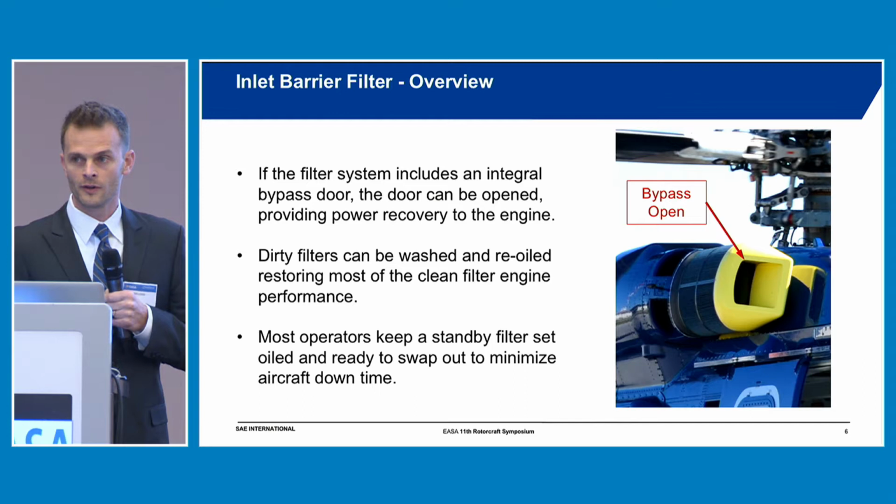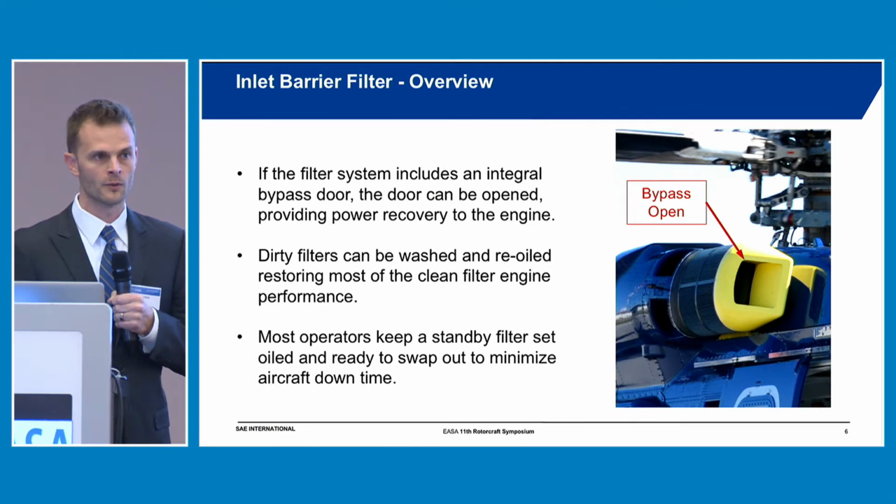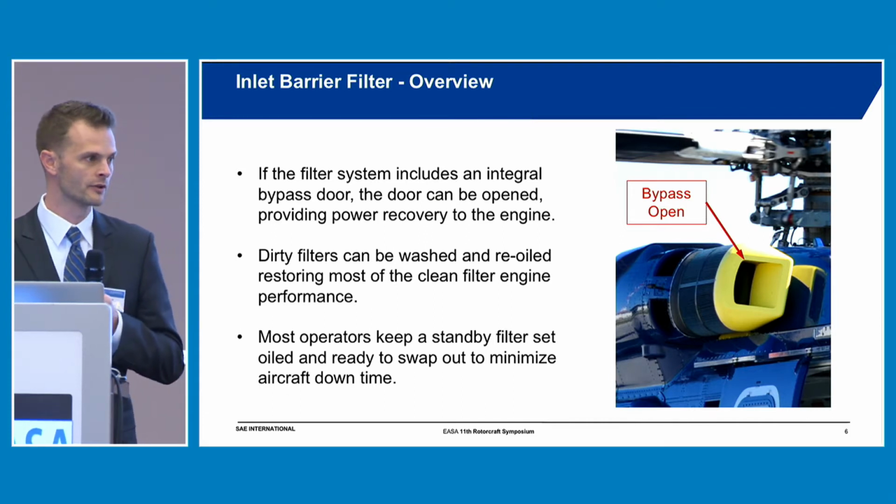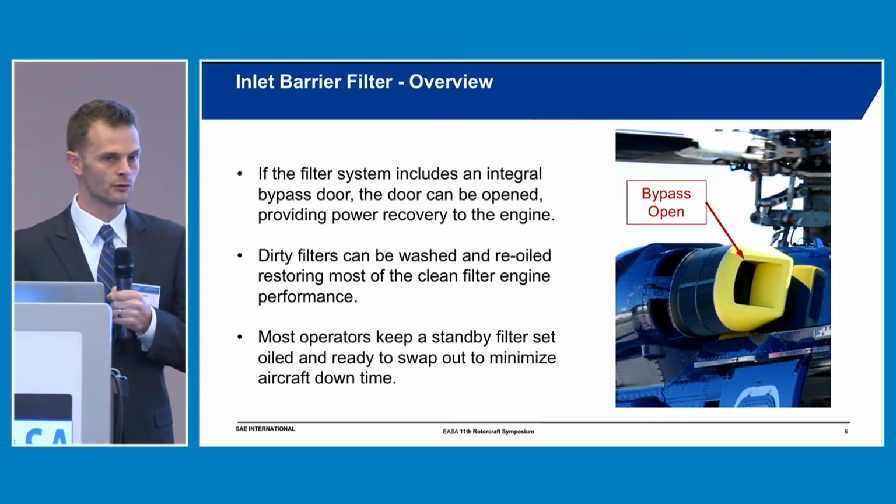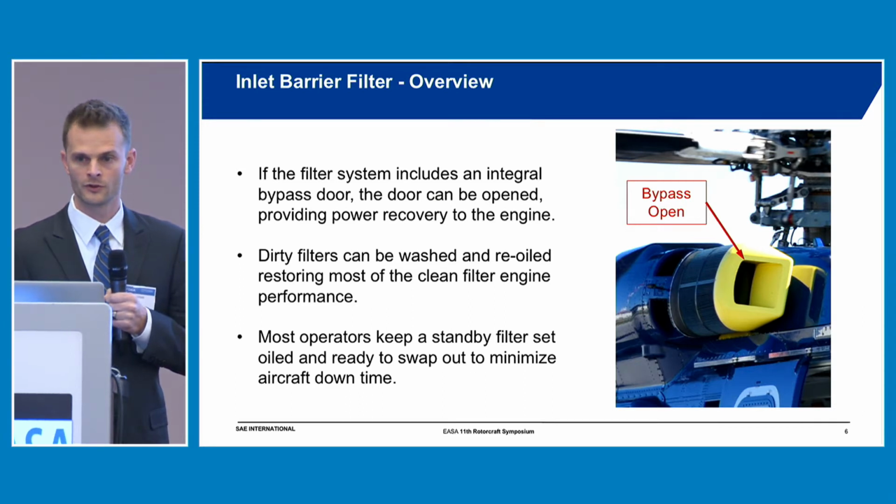The dirty filters can then be re-oiled or washed and cleaned and re-oiled, and typically that would restore most all of the clean filter engine performance. In general, we find that most operators keep a standby filter oiled and ready to go to decrease the downtime, which is often approximately 24 hours to clean, dry, and re-oil an oil-type media.